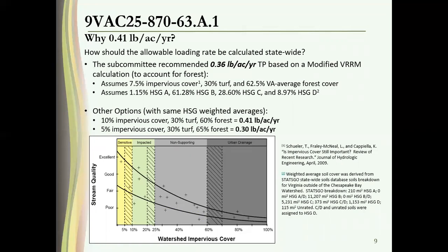And the main thing is the soils underneath. Are they well draining or poor draining soils? That's what the HSG-A, B, C, D stands for on that slide. Engineering talk. And then you have to consider your land cover. Does it have already impervious surface? Does it have trees, or is it just managed turf?